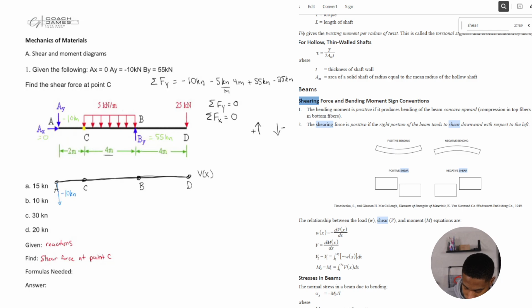And it's important to note, this is our negative, that's our line for our -10. So if I was to come down further, it might be -20 kilonewtons. But in this case, since our force at that point is -10 kilonewtons, then that's what our shear is at that point. All right. And it's important to note that your shear stays constant if no other forces are acting.